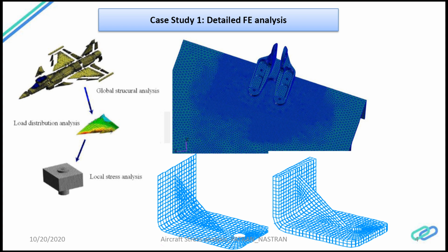And also, when they give you a load, you should be able to mark the tension clip. Imagine a bracket like this. There was a question like this in my interview when I attended. In some of the companies they give a bracket with two fasteners on either side, and you apply a load. They would expect you to say what kind of loads the fasteners would take. Those kinds of free body diagrams for the shear clips and tension clips, and these kinds of brackets, you should be able to mark.